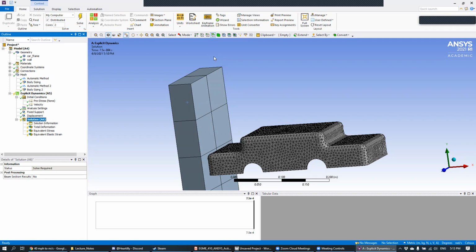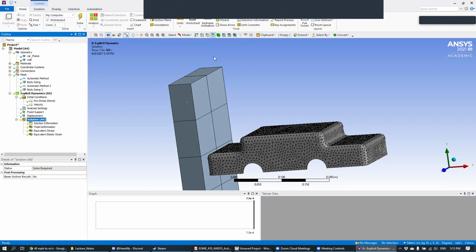Yeah, that's tough because the most accurate thing would be to do a simulation of the entire system. How that load transfers to that one component is often difficult to determine, so we need to perform a simulation on the entire thing to get that correct. What you can do, since you know what component you're interested in, is make that component have a really refined mesh and have a fairly coarse mesh everywhere else, just to make sure that you can run the simulation.